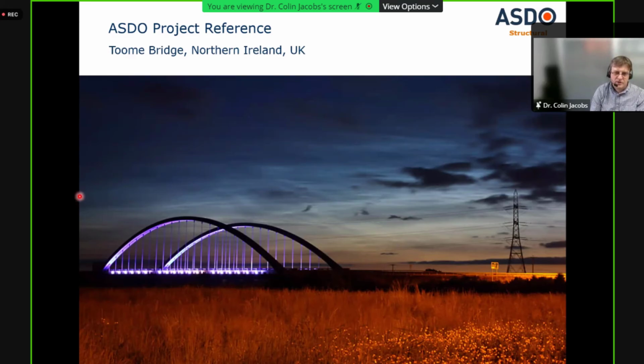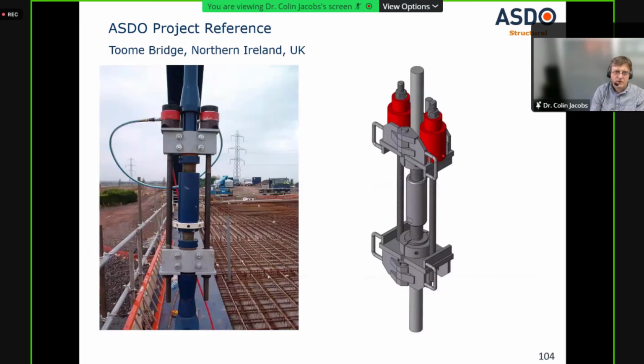Another road bridge, again, you've seen this shot before, the bridge in Northern Ireland, again just showing how the stress is put into the tie rods. So any pre-stress you want to put, maybe a pre-camber into the deck, can be done quite easily with this type of equipment.